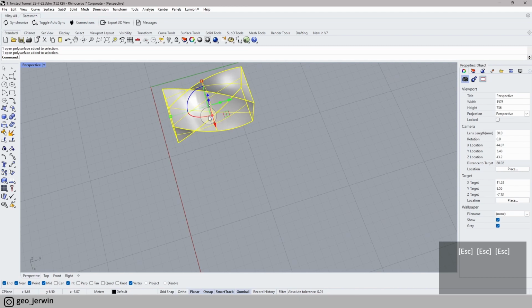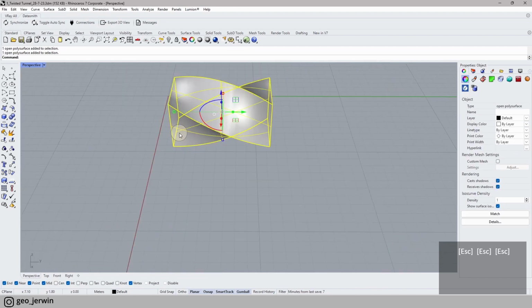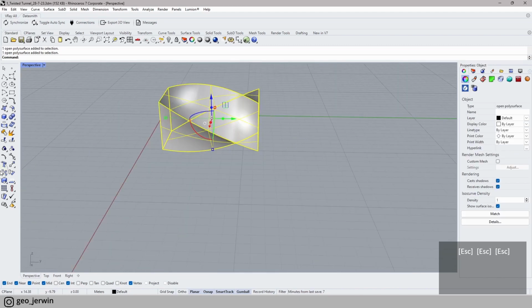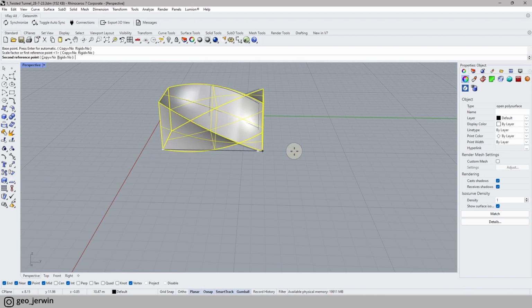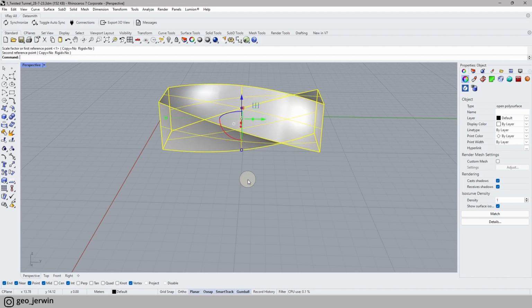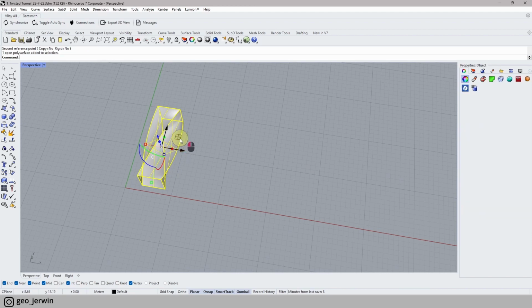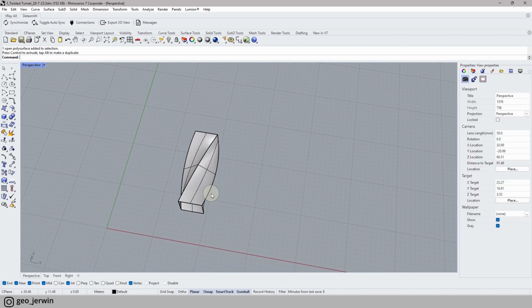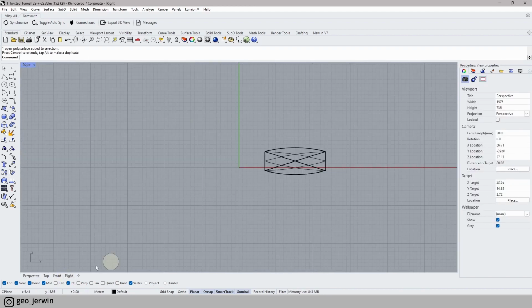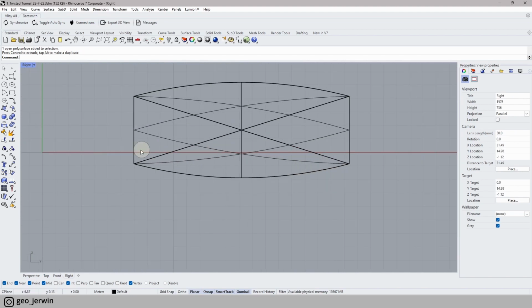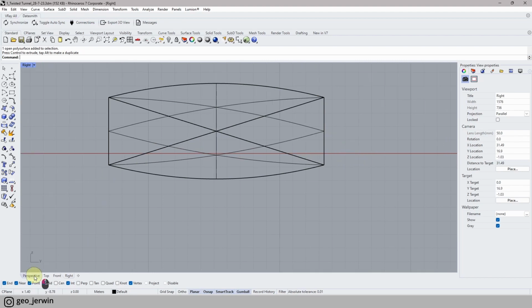And let's say I want to increase the length of it a bit. I can scale it in 1 dimension using this tool, Scale1D. I'm going to scale it to a certain extent like that. Cool, that seems all right. Now, let's move it a bit further from the origin. That's fine. Now what I'm going to do is cut this from here, so I can get a proper base for this tunnel.